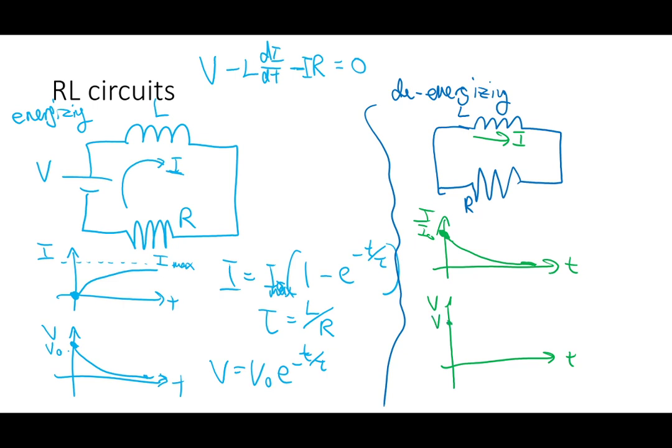And so that's why, likewise, you're going to have a bunch of voltage to start with, and then your induced voltage drops to 0 as your current becomes stabilized. So in this case, both of these would be your decaying exponential with the same tau. So very similar to your RC circuit case, all you're doing is working out what tau is and then picking out the right function, whether you're energizing or de-energizing, talking about current or voltage or whichever.